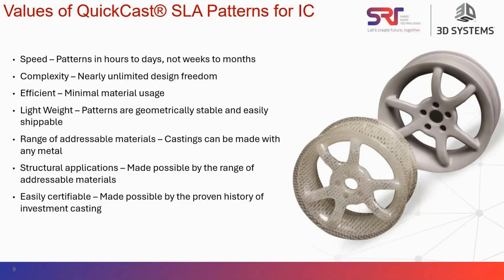So finally, because of the quick iteration, if you would like to test a component or get certification, investment casting has a long history of producing metal parts. We are just changing the pattern production. So you don't need to worry about how the part is going to be manufactured, and it can be produced very quickly. I would like to play a short video about QuickCast pattern production